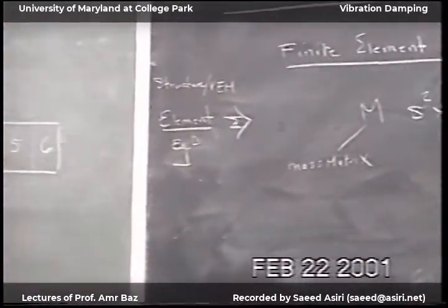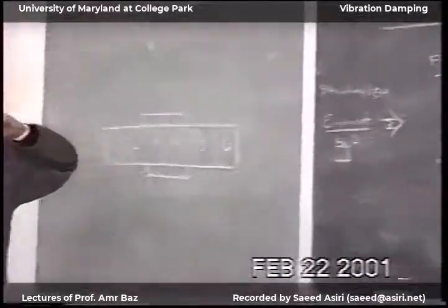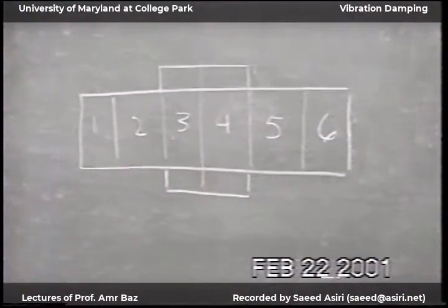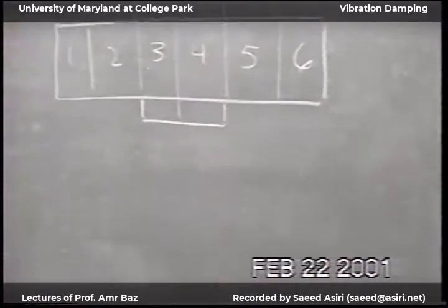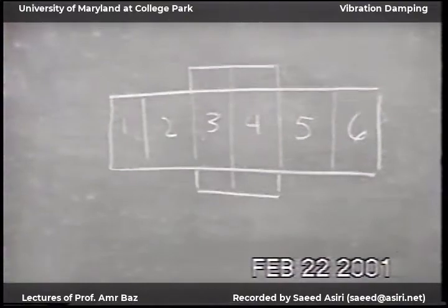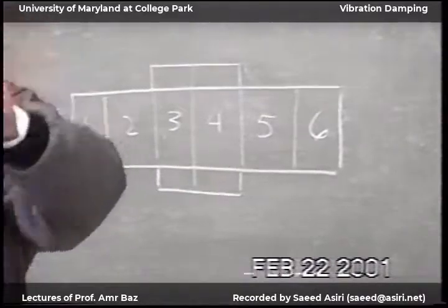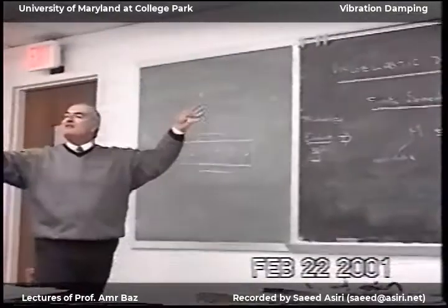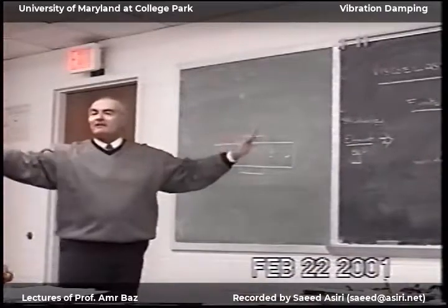And again, this is the way to do it. You cannot put viscoelastic material everywhere. Viscoelastic material adds weight, and you have to minimize the weight. So in many applications, like maybe I've showed you the drill that we did for Black & Decker. You cannot put viscoelastic material everywhere because this will raise the price maybe 50 cents. They don't want to buy it. Same for cars. We did a project for Fiat. They want only $30 worth of viscoelastic material, no more. So the car is $10,000, but you can only put $30 of viscoelastic. So you cannot put it everywhere.